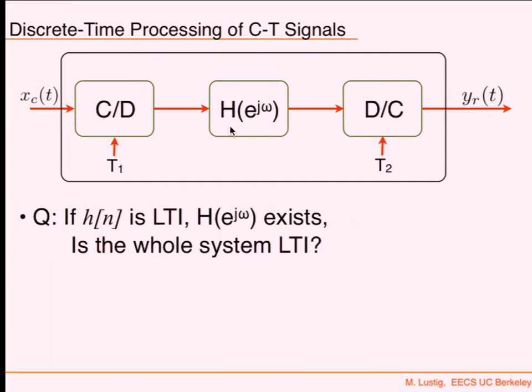Is that LTI? No. Why not? I don't think it's time invariant, because if you shift the signal... Yeah, I'm shifting my signal. You hear it? Yeah, but in the C to D converter, if you're multiplying by a chain of deltas, let's say that your signal happens to be positive where those chains intersect, but zero otherwise, and then you shift it, then you're going to get a zero. Okay, let me ask this: is the system from my microphone to the speakers LTI?